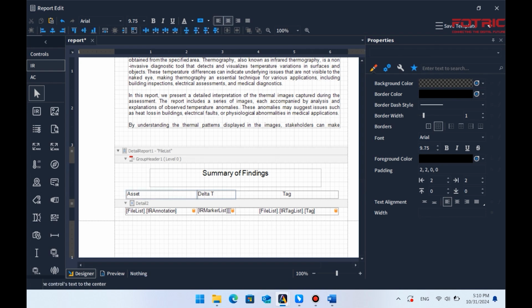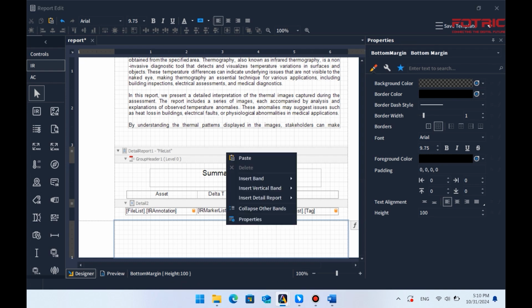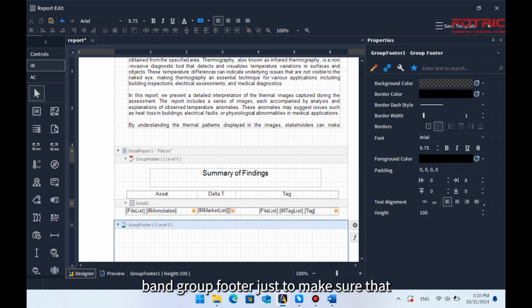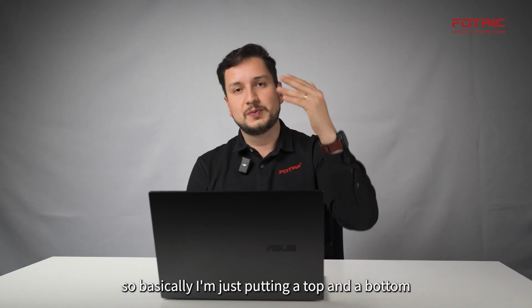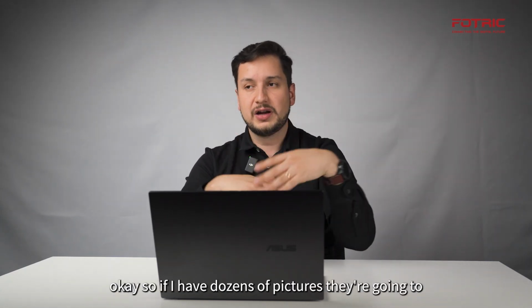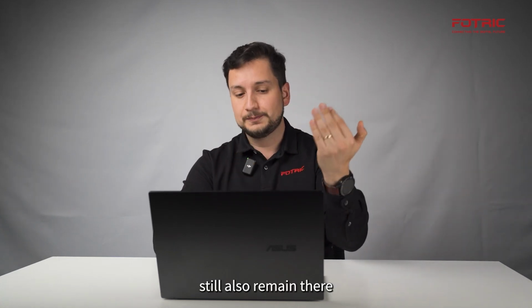This one also. Okay. All right, so right here I'm gonna add a band group footer, just to make sure that whatever is between the group header and the group footer is going to repeat and is not going to get into other sections. So basically I'm just putting a top and a bottom to contain everything in between. Okay, so if I have dozens of pictures, they're gonna still also remain there.